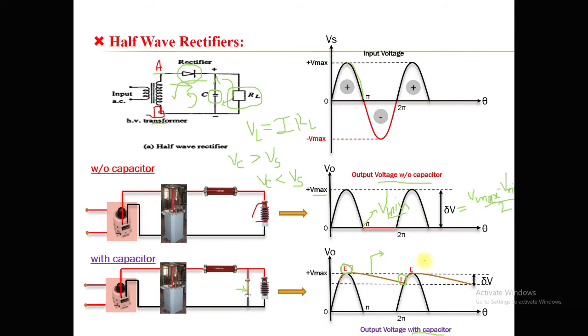One point which we need to understand in this case is the alpha t term. Here you can see there are two things. This is normally known as the conduction time. Conduction means the time from which the diode starts conducting, because it needs a minimum potential to conduct.